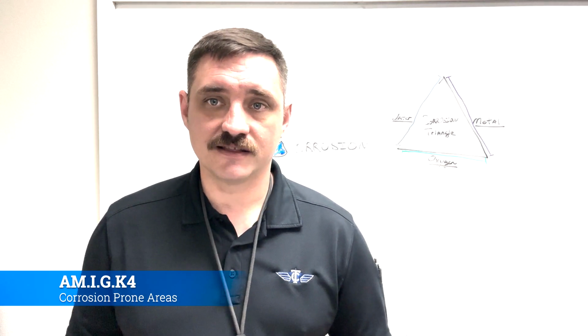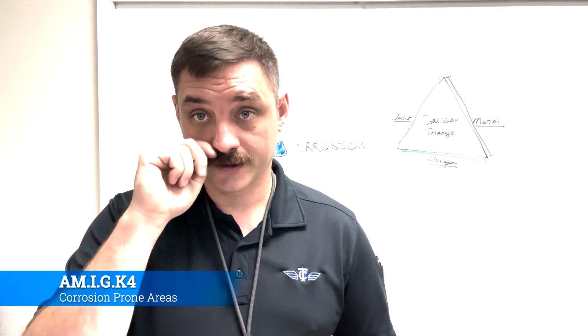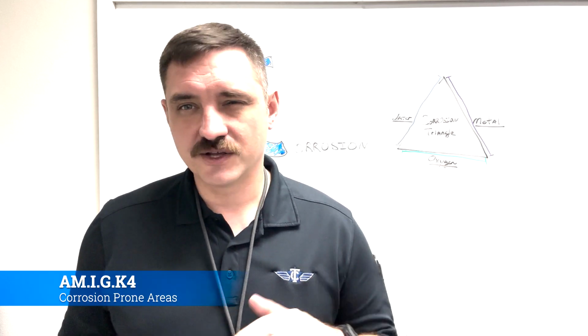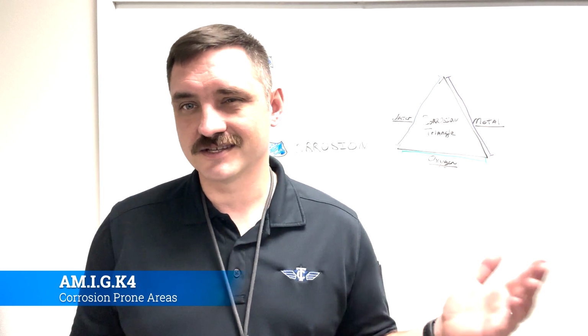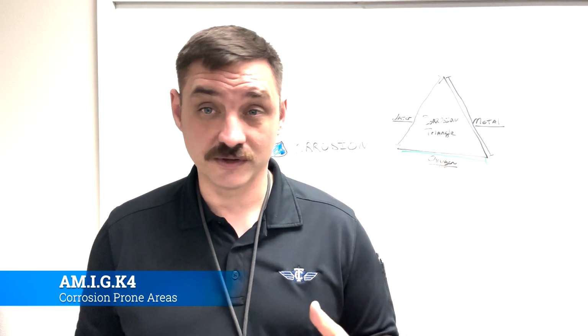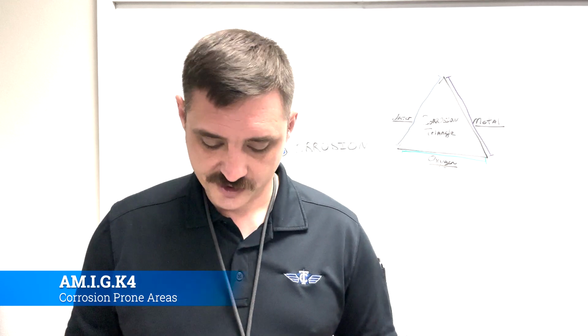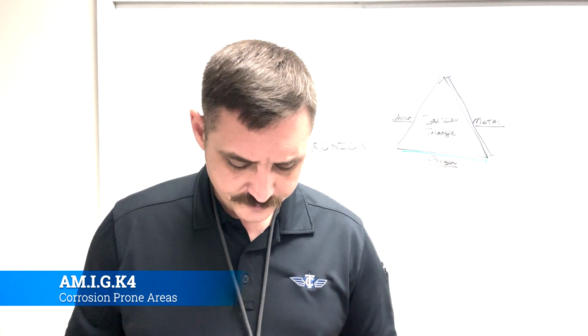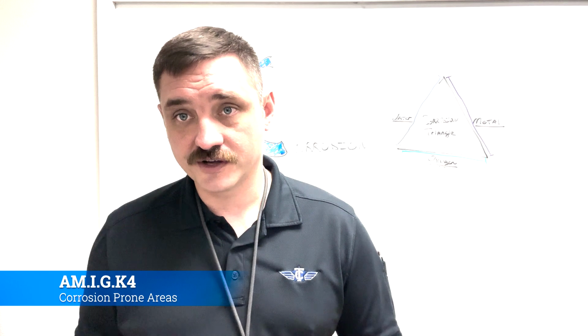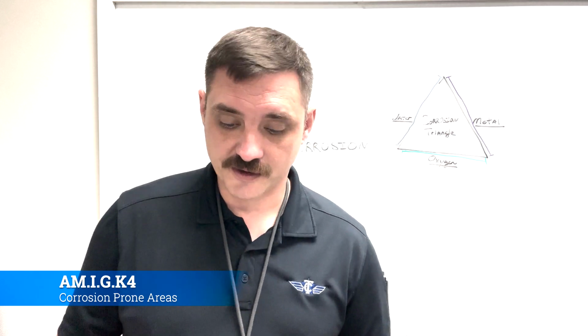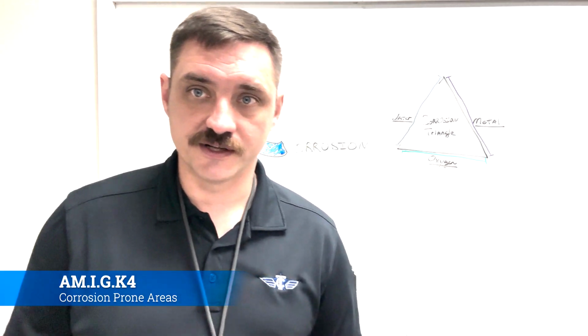So like on the Aztec, the engine cowlings have a piano hinge joint that comes down. I'll tell you that it seems that as time goes on, people get further and further away from the piano hinge, both because it's just a hassle. They're not fun to really mess with, but they're also a corrosion powerhouse. Corrosion of metal skin joints made by spot welding is the result of the entrance and entrapment of corrosive agents between the layers of metal. So anywhere that there's two metals coming together, you can bet your bottom dollar that there's definitely going to be a chance for corrosion in there.